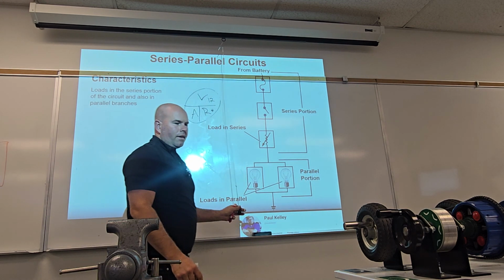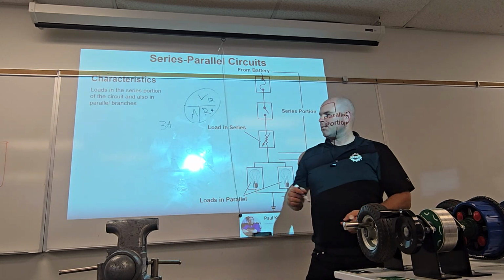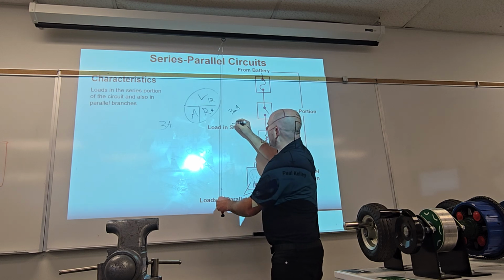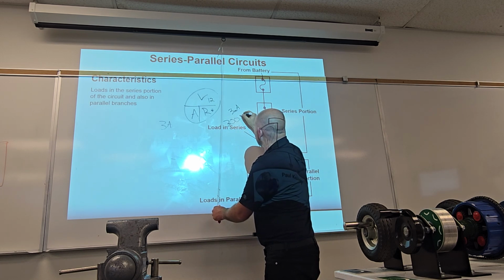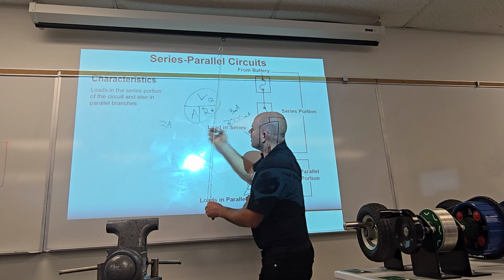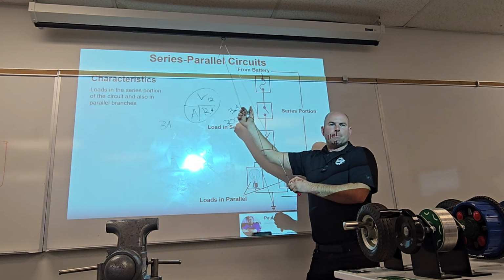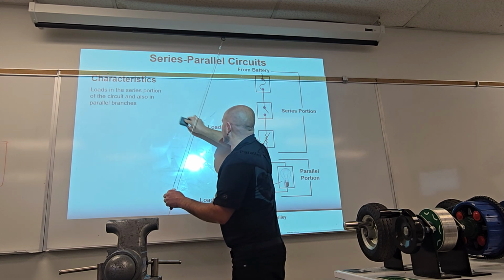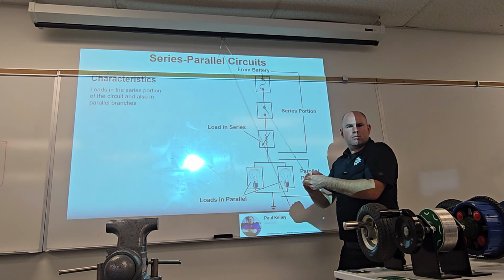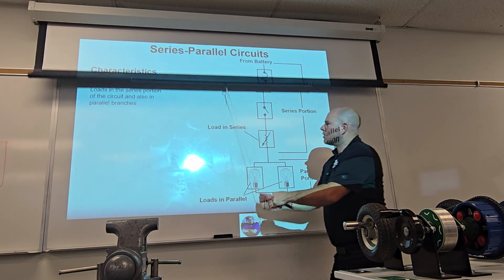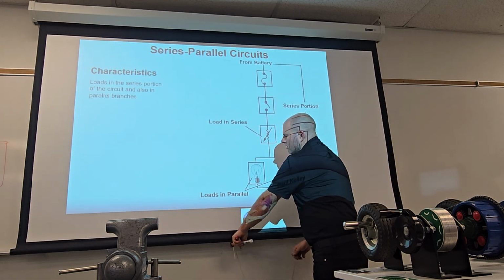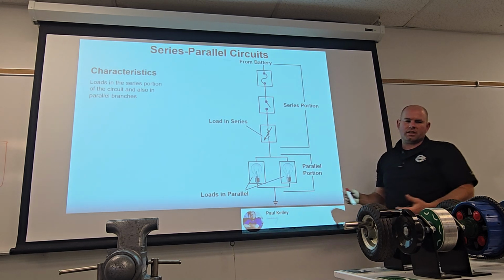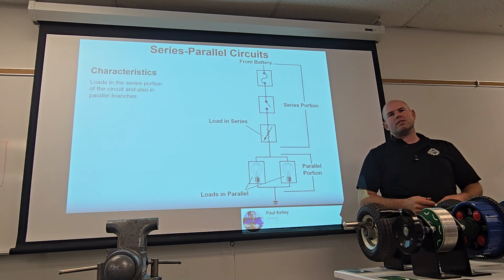Your computer is not happy right now. Your computer wants to deal with like 3 milliamps, not 3,000 milliamps, which is 3 amps. Make sense? So that's how you let the magic smoke out. So test lights are a good tool. I feel like it's worth discussing, but going forward, as things are more computerized, you just got to remember when you hook a test light up, you're potentially overloading a computerized circuit.